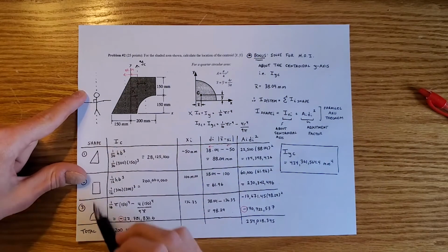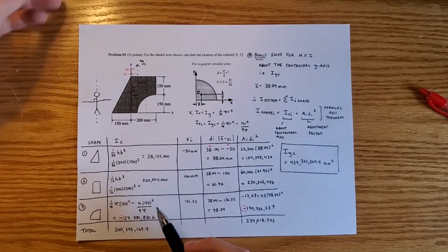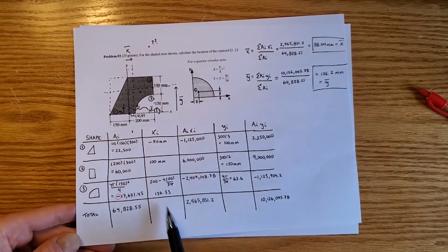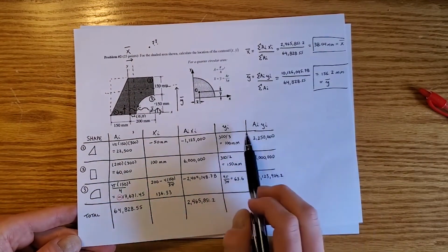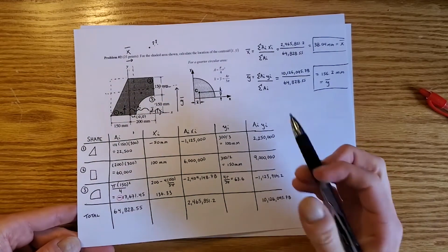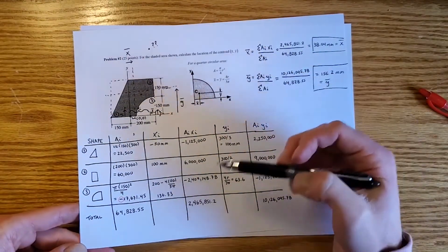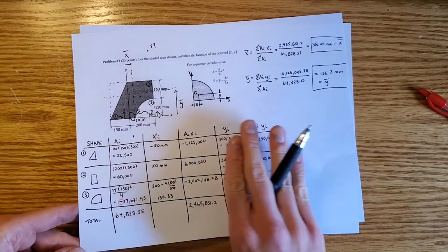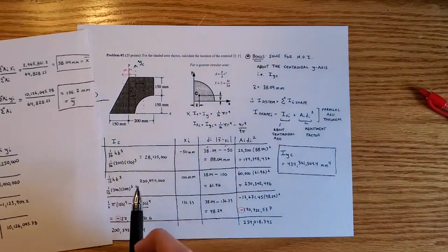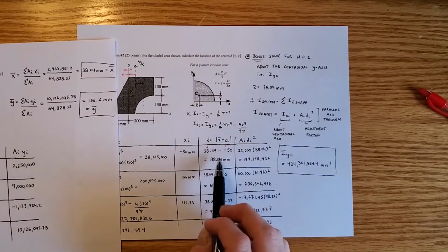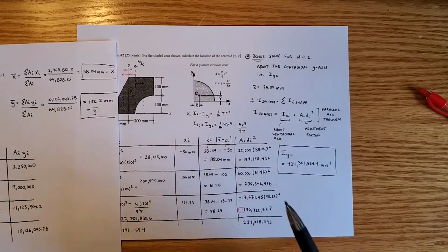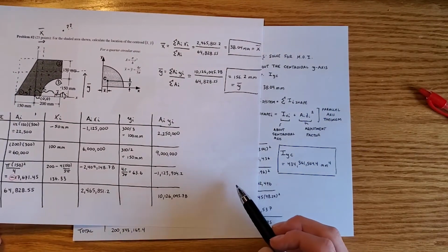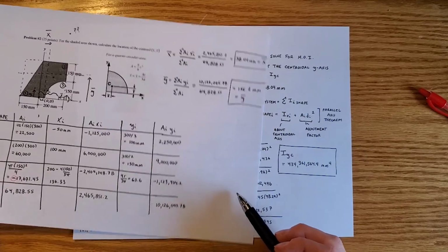Now, I find that the table is very helpful because if you combine your table from the previous part, you can keep your A_i, your x_i, and you would just be adding a few more columns to the right. Because usually on the exam, you won't be asked for both x bar and y bar, you'll be asked for one or the other. So we would cancel out these two columns here. You would add in essentially this column and these two columns right here, and you would be able to get your answer much more easily and much more efficiently and neatly, which we always like when we're grading the exam.